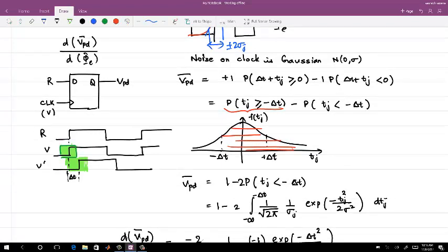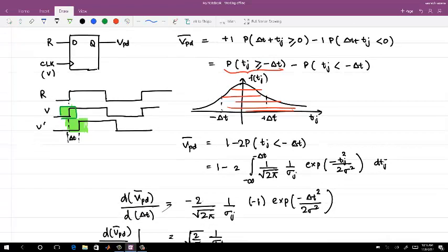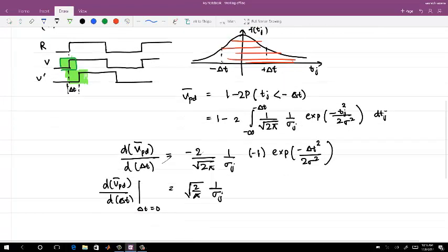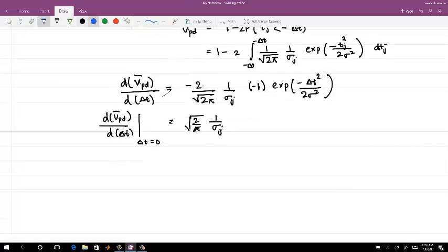So in a PLL you may not use it, but in clock and data recovery, in a bang-bang phase error detector, because you are operating at a very high data rate, you cannot employ any complicated circuit. Okay, and the analysis of a single D flip-flop used as a phase error detector goes like this. Any questions so far? So this completes the part on the phase error detection.